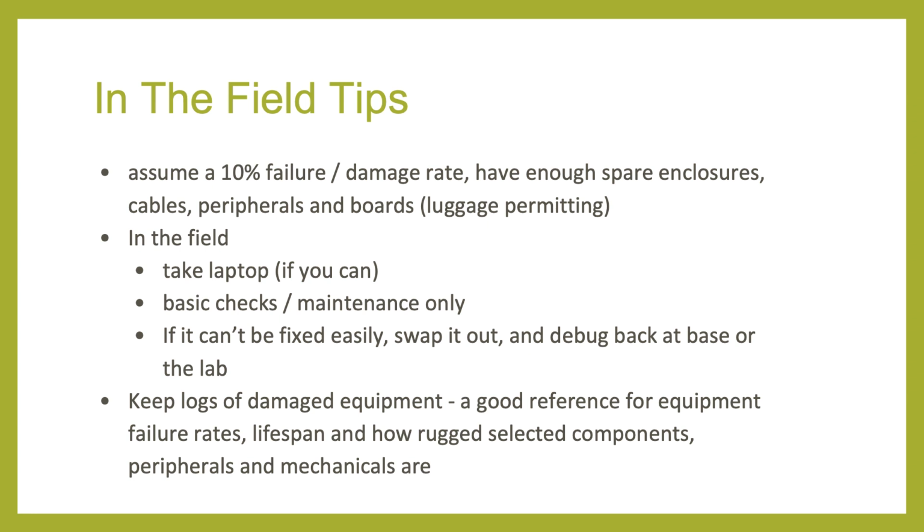We also take our laptop into the field. However, we generally only do basic debugging, checks, and maintenance. If we can't fix the issue on the spot easily, and we have enough spares, we'll just swap the device or damaged part out, and then debug it more thoroughly and fix it back at base or in the lab.